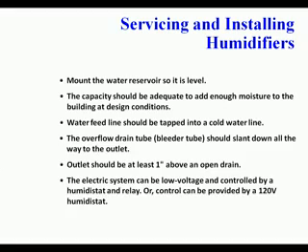To service and install humidifiers, mount the water reservoir so it's level. The capacity should be adequate to add enough moisture to the building at design conditions. Water feed lines should be tapped into a cold water line, and the overflow drain tube or bleeder tube should slant down all the way to the outlet. The outlet should be at least 1 inch above the open drain.